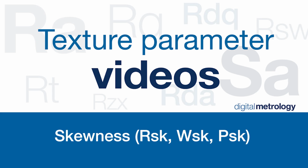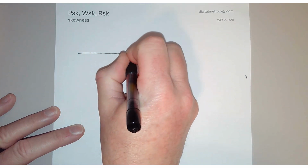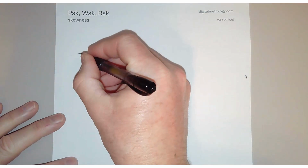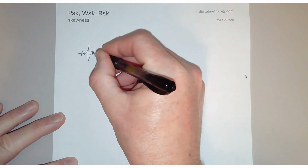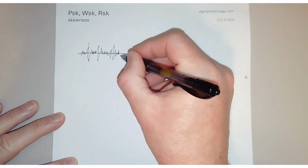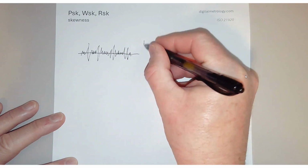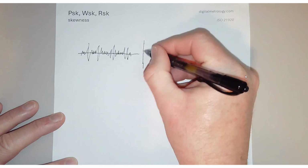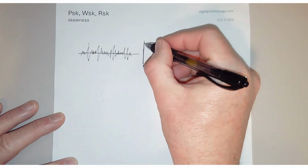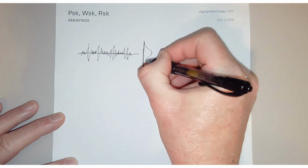In surface texture analysis, skewness refers to the distortion of a surface upward or downward. In fact, it's probably better to describe skewness, like the roughness parameter RSK or primary PSK waviness WSK, in terms of how the distribution of heights look. So this surface is rather symmetric. I have similar peaks and valleys, and the distribution of heights is kind of like a symmetric bell curve.